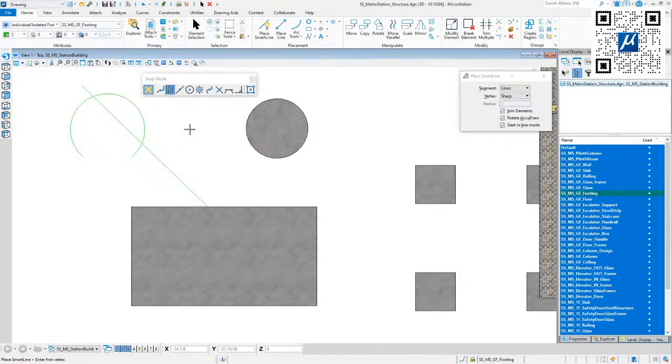And yes, we have that feature that we can get multiple snap points together. It's also a question that I get very often in trainings. People come from AutoCAD and they say, "Hey, we have to change the snap mode so often." No, you don't have to. There's a multi-snap option. So if you don't want to change your snap mode that often, simply use the multi-snap. And from multi-snap, you can do some settings. So I can combine intersection, key point, center, maybe. I don't like that nearest. So these three are my most common or favorite snap modes.